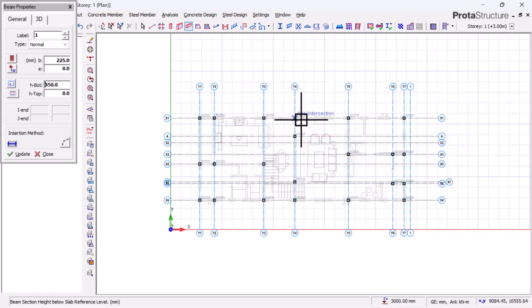There's another thing. When the distance between two columns becomes so much apart, then you are increasing the chance of having a high tensile member, a higher reinforcement in your beam. But when your columns are closely spaced, then you have a slim chance of having a higher reinforcement in your beam detail by the time the output result comes out.